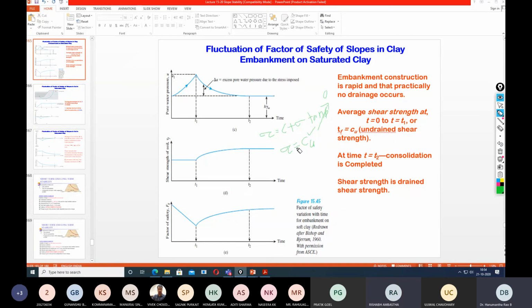That means your shear strength equation will be transformed from initial tau equals Cu to C plus sigma tan phi. So this is how the shear strength improves. You can connect this to the Mohr circle diagrams, how the slope is increasing as you go from UU to CD test.